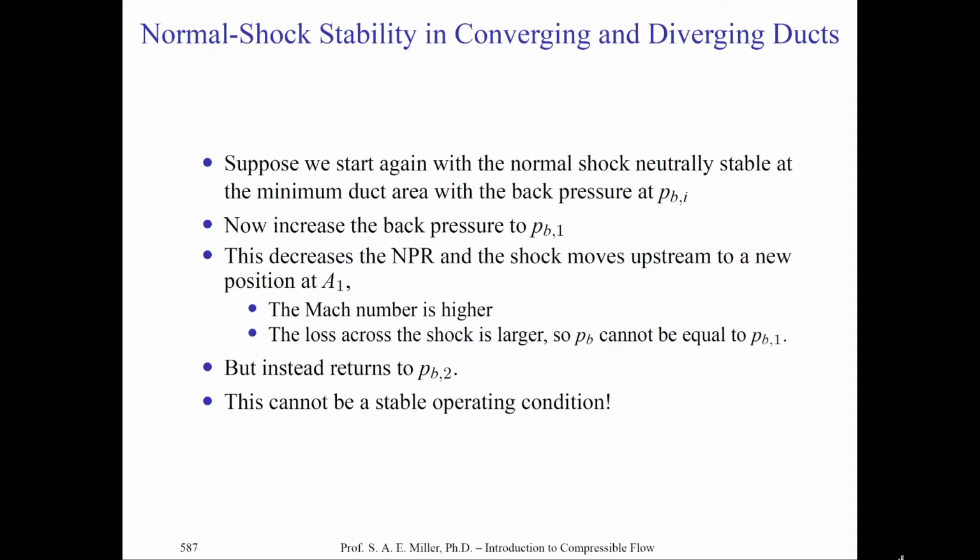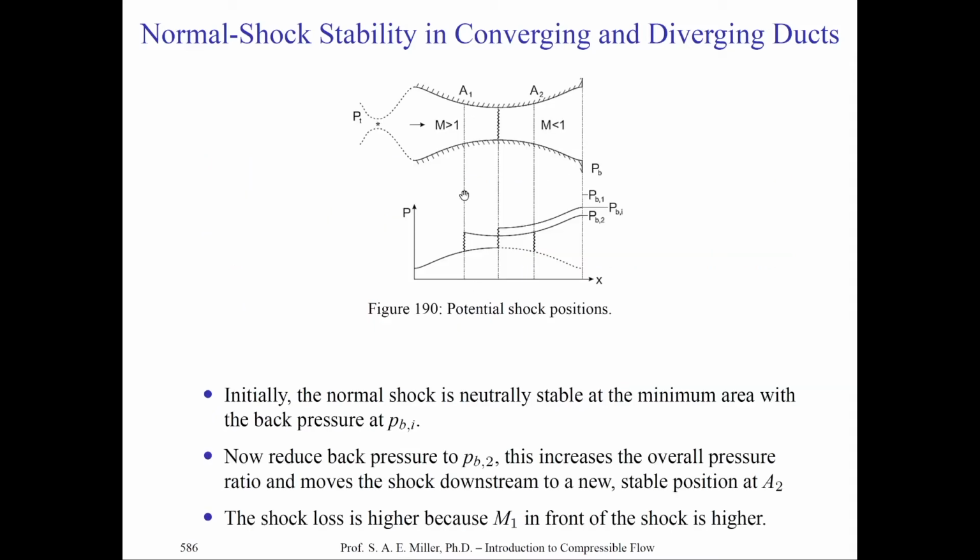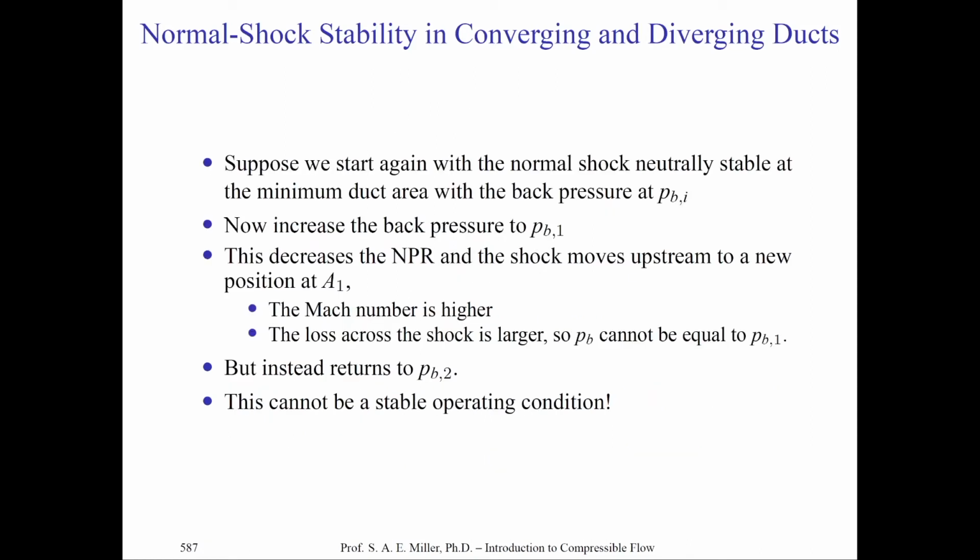And you can see, since the shock wave in the divergent section of the supersonic diffuser will only give us a back pressure of PB2 and not PB1, which is what is desirable. And what does this mean? This means that the shock cannot stably stand there because, of course, we're not matching pressures. And that imbalance will accelerate the shock downstream or upstream, depending on the tunnel configuration, because the back pressures are not matched. So you can see, indeed, this is what we call an unstable operating condition. It is not stable.